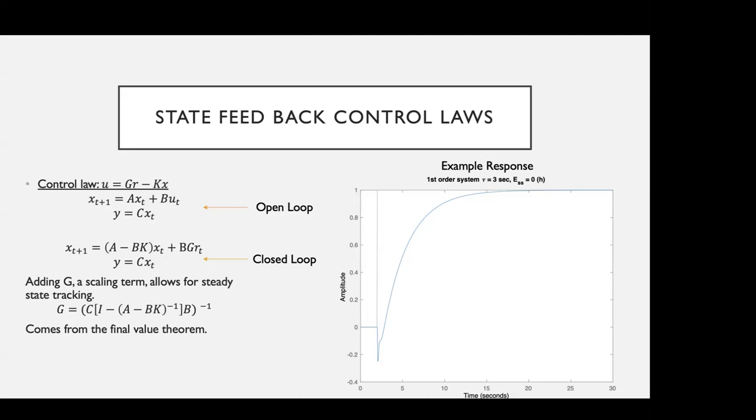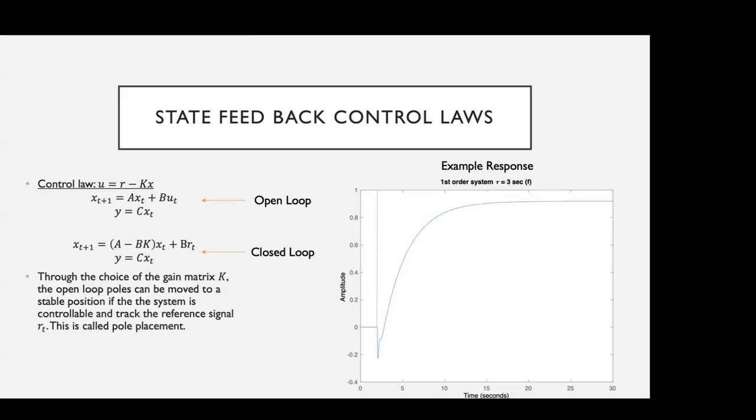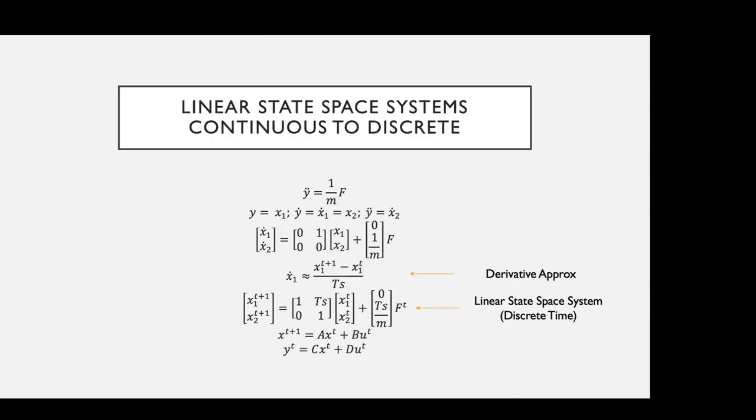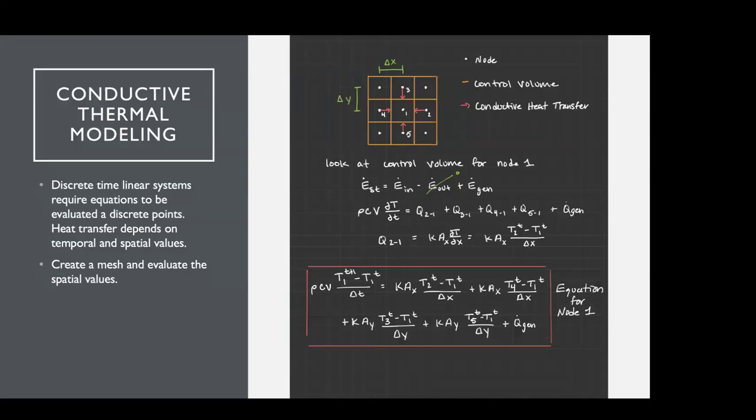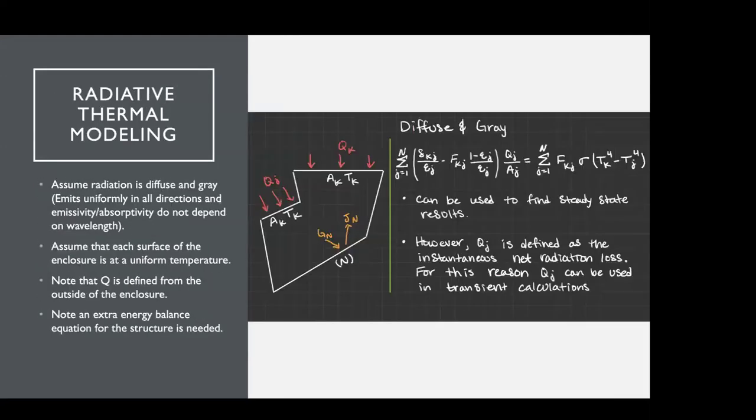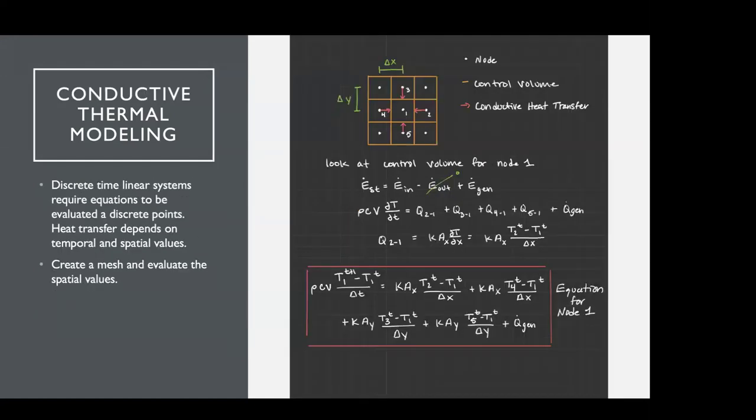I also had a question about your enclosure boundary. You said it's cooling to vacuum, radiatively. I assume that was the CMB. Do you also have solar heating as a boundary condition? No, I did not model a solar flux, but you could do that. It's pretty simple. I think it would be a boundary condition term. You just add another term in here for each node.